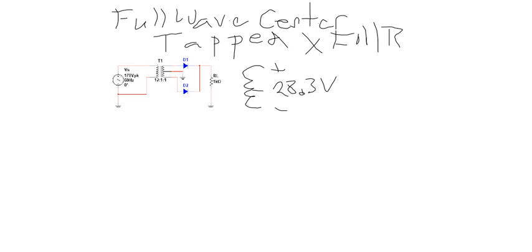It's like we had a circuit that looks like this, where each of these voltage supplies represents half of that secondary coil. So it splits the voltage in half. But notice the polarities. If I put in a sine wave, on this side I'm going to get a smaller sine wave, but the same polarity. Down here, I'm going to get the same size sine wave as I had on top, but the opposite polarity. So when this one's positive, this one's negative, this one's negative, that one's positive.